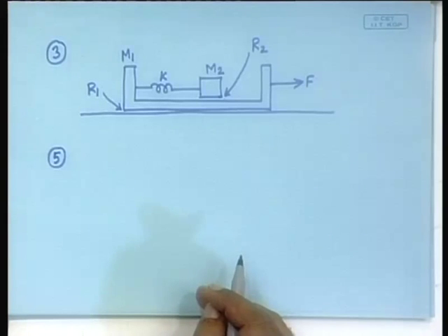This problem will concern the way the loudspeakers work. So, how does the loudspeaker work? It is an electromechanical system, right? A loudspeaker is an electromechanical system. There is a magnet which is energized and that pulls a diaphragm which oscillates. The diaphragm pulling and other stuff, that is a mechanical system. The other thing is the electrical system, and in between there is a coupling through magnetism, which is similar to the DC machine problem that we did.